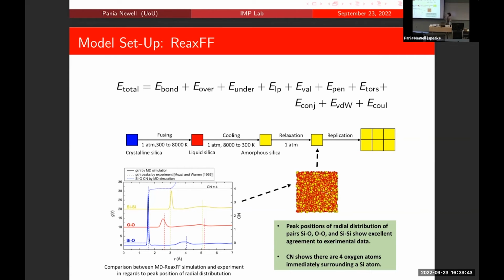So the question is, when you start with crystalline materials and then create these amorphous structures, do you get the same structure, the same properties, or are you messing up the whole response of the material? That's why we have the radial distribution functions, which confirm that this amorphous structure, where we just change the orientation, has the same property.